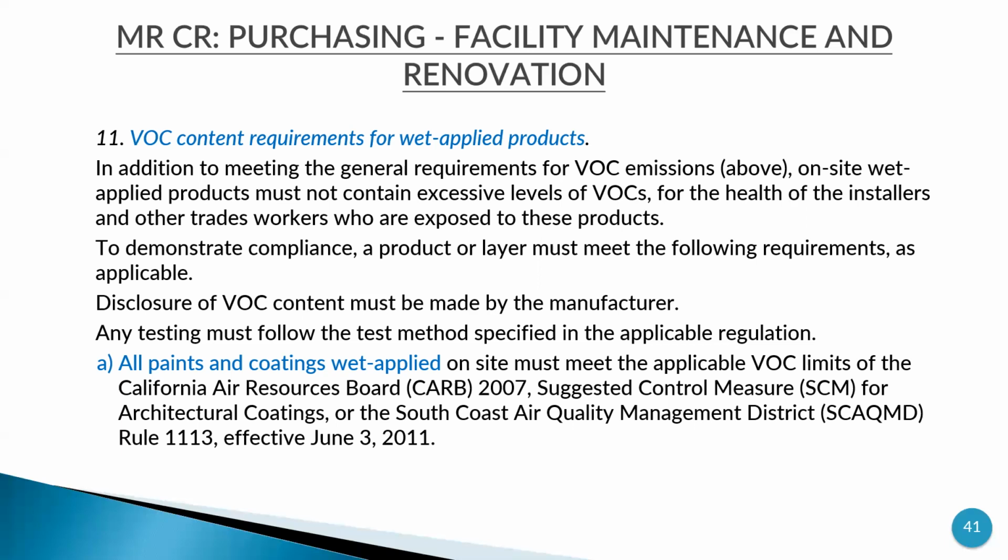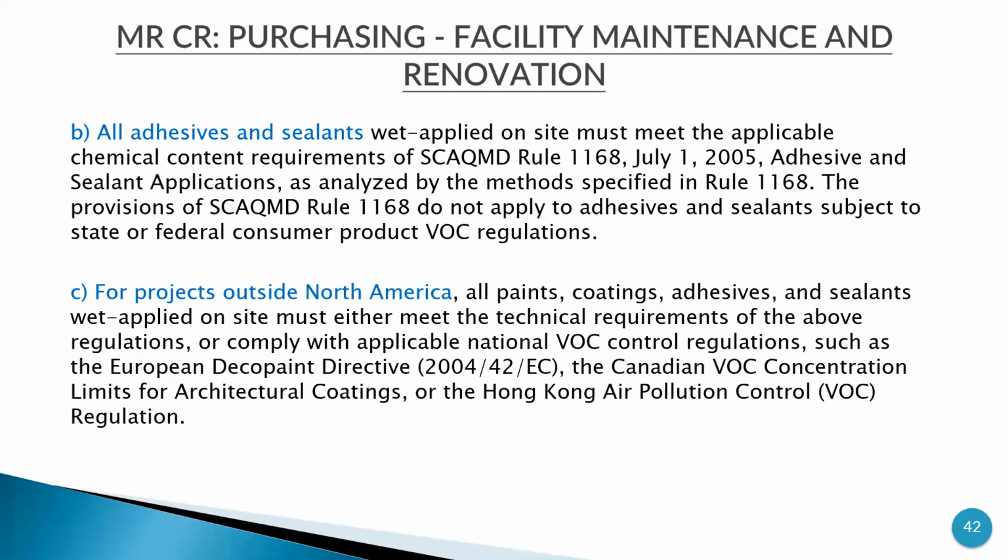To demonstrate compliance, a product or layer must meet the following requirements. Disclosure of VOC content must be made by the manufacturer, and all paints and coatings wet applied on site must meet the applicable VOC limits of CARB, the California Air Resources Board, suggested control measures (SCM) for architectural coatings, or the South Coast Air Quality Management District, Rule number 1113, effective June 3, 2011.